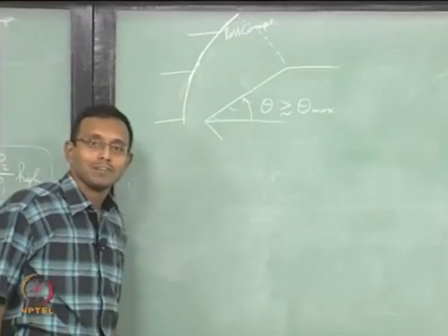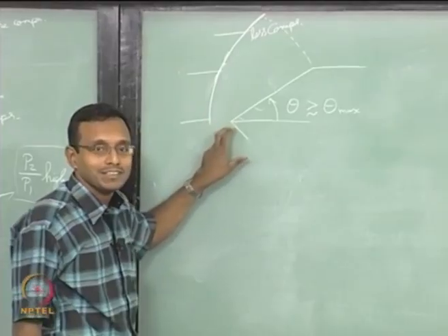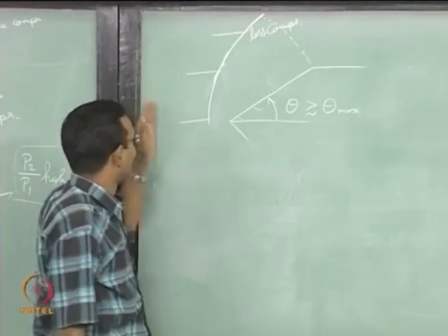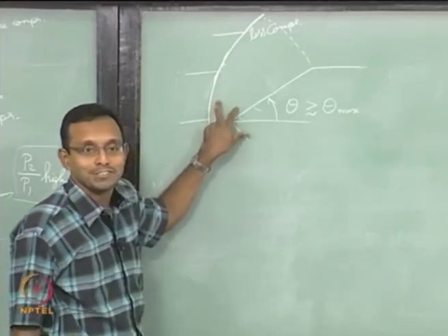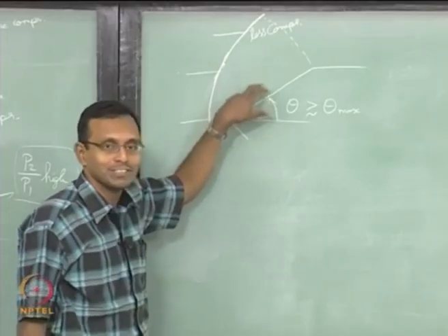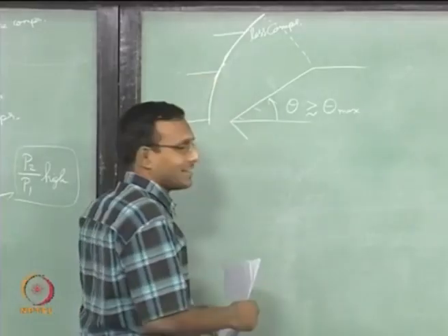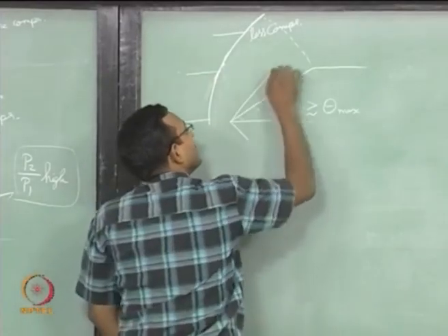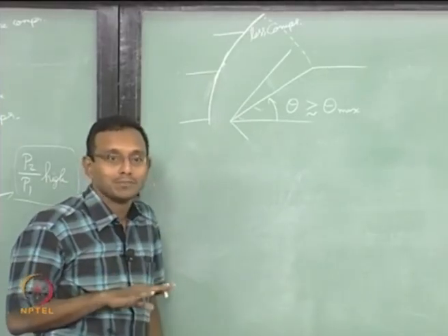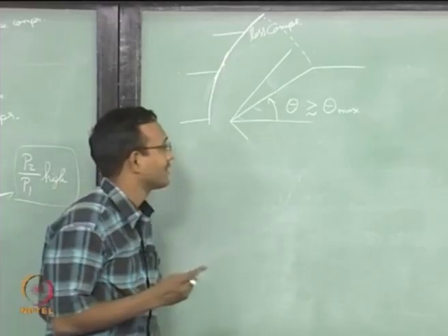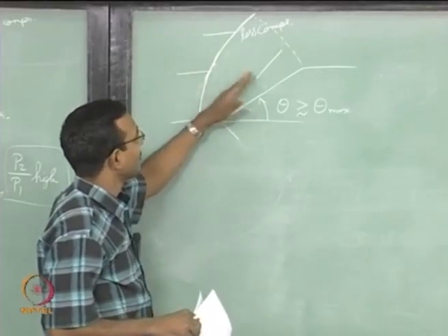If the gas is more compressible, what should happen? This gap can now be decreased. Why? Similar to the weak shock answer, the flow incoming can push the wave more back and keep the gas behind more compressed, because it is more compressible. It is possible to compress, let us compress it. Okay. That is what it does. So, when that happens, flow can get attached. I am just giving you a possibility, I cannot give you an exact answer because nobody has proven it exactly this way. Okay. I will just give you that there is a possibility of this getting compressed to a point where it gets attached.